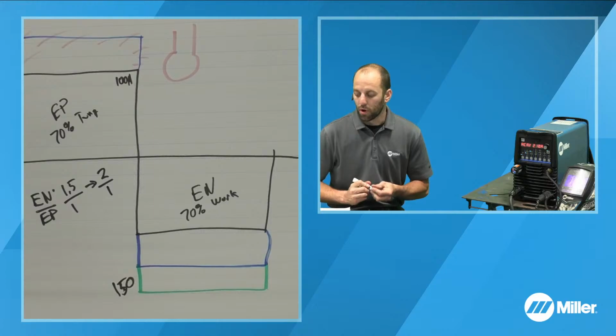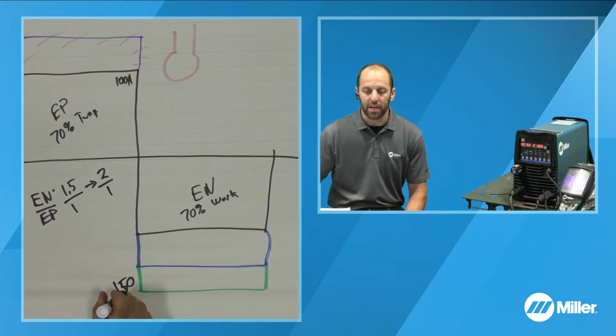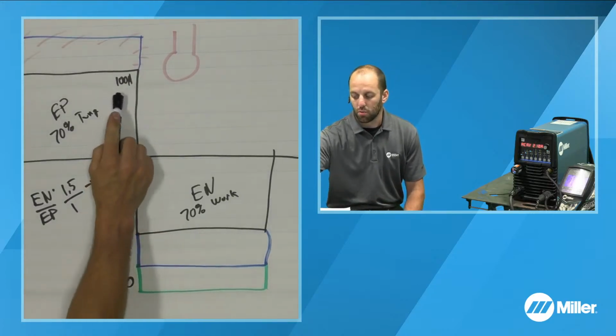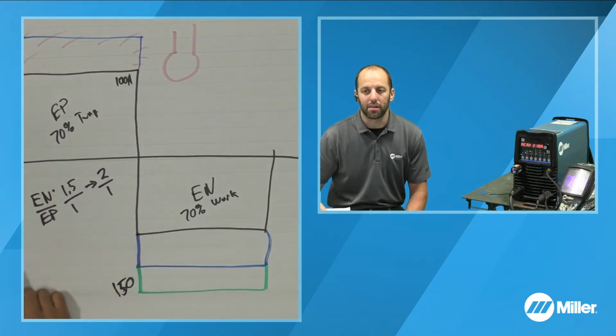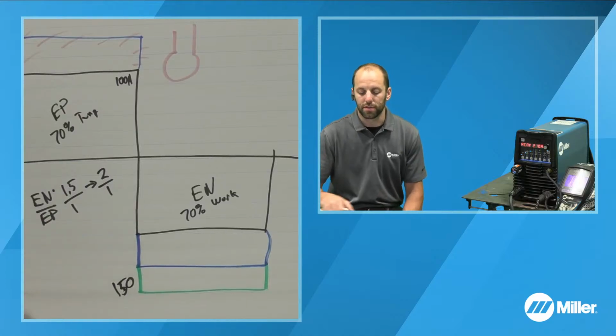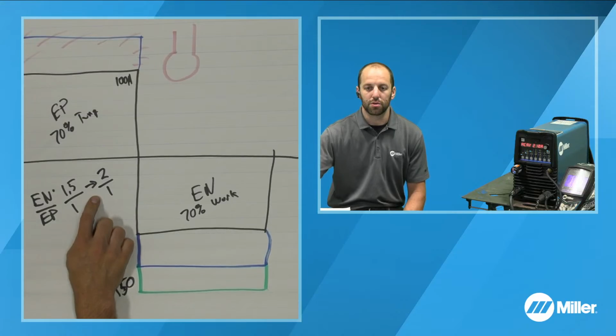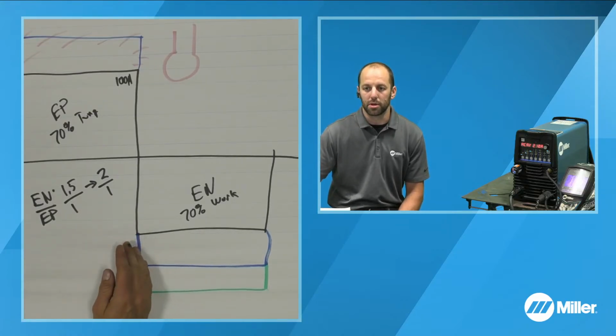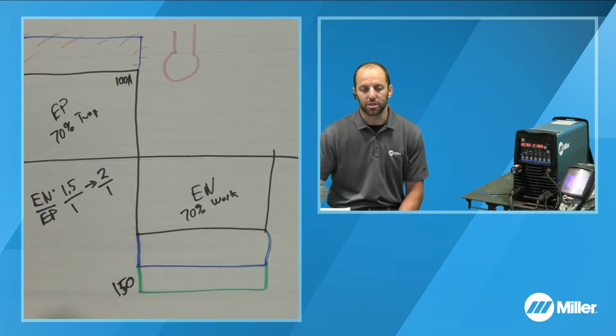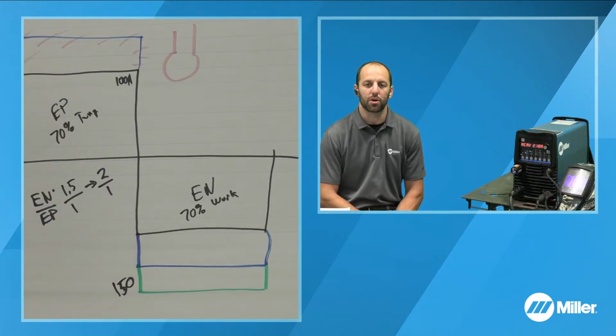And what that's going to do for us, like I said, is give us extra heat down into the workpiece while reducing the heat on the tungsten. We're still going to use our balance settings accordingly to look for that black peppering like we talked about last week. But this is a great way to not only stretch the machine and get a little bit more heat into the workpiece, but also stretch the consumables a little bit further than maybe we could have in the past.